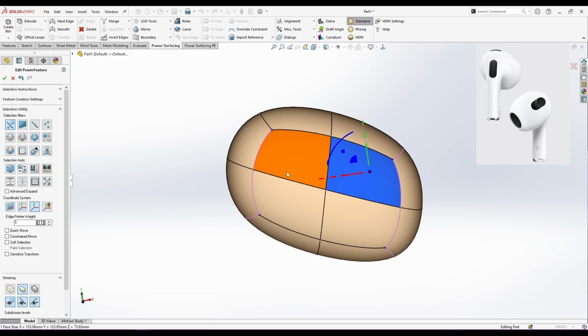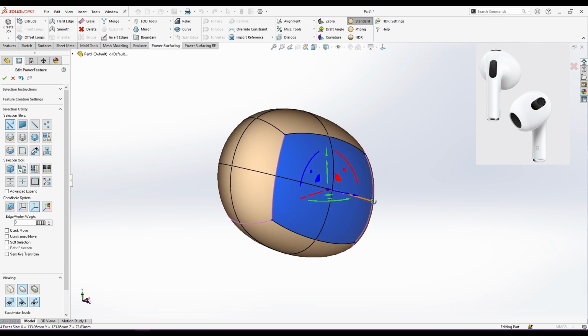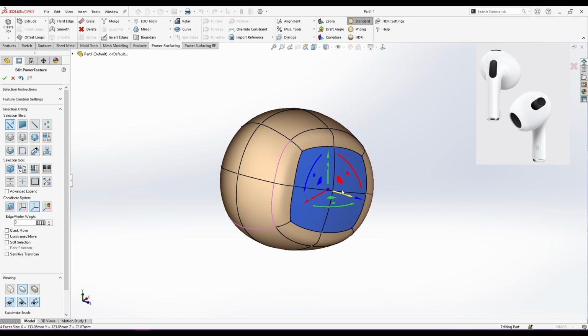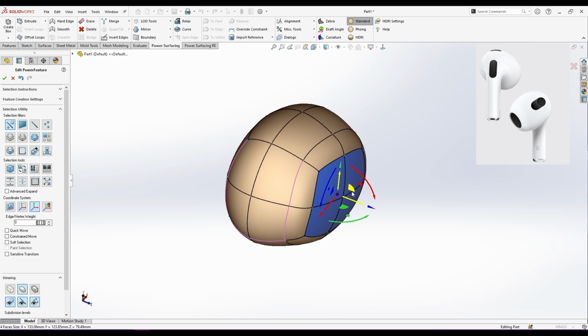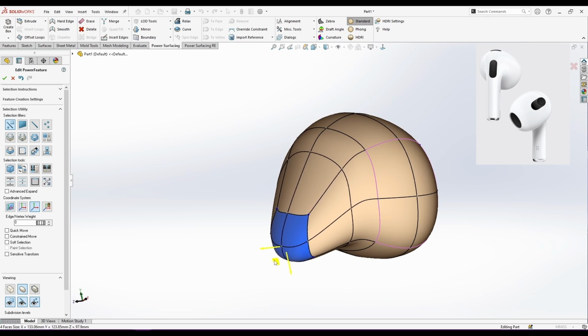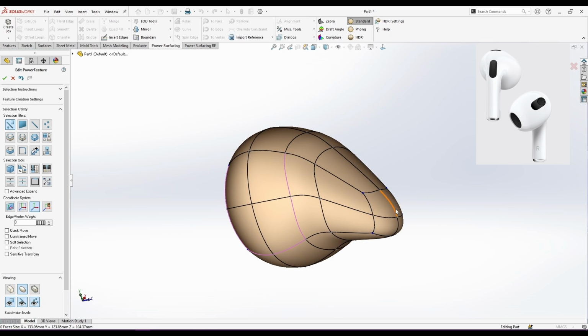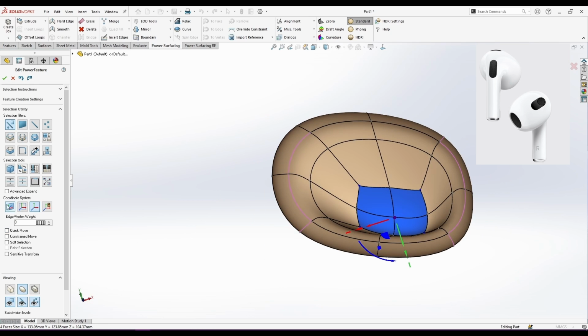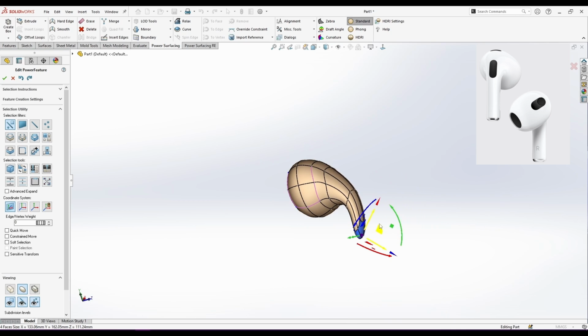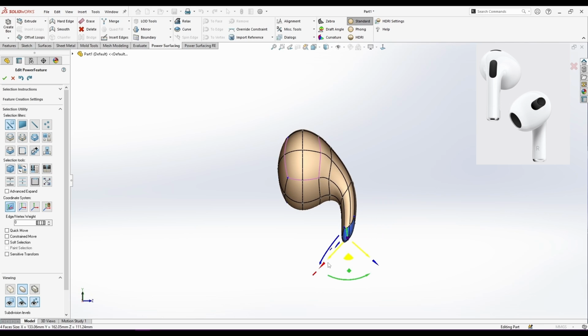So I'm going to select these four faces and bevel, holding the A key, extrude, and extrude again. Scale a little, something like that. I'm going to rotate it a little and then extrude again. Now I'm going to select the orientation to be coordinate system to the world and raise this 100.